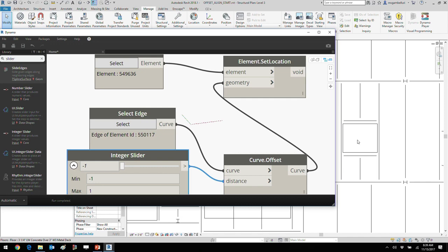Ooh, it gets better, right? So you can use this script and run along your beams and do this. It may not be 1 foot, it may be 6 inches. Make sure you consult that architect, because at this point in time, I imagine that the architect has done an entire study of all the interior slab edges and how it would affect all the wall ratings, and they would have fully detailed each intersection and cut sections all the way around to get you an educated professional decision on where that interior beam should sit relative to the edge of slab, right?